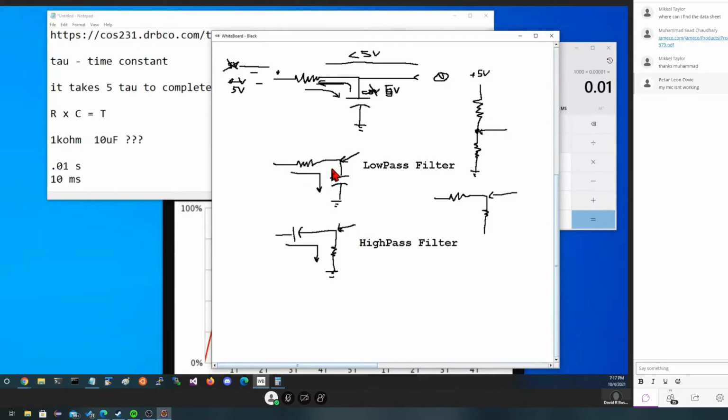Meaning that from here to here, even if you're passing very slow moving signals, like DC, where it doesn't change at all, we will see the result of that right here. It'll basically be the same as though that signal coming in is filling this up like a bucket. And when it's finally full, basically anything passes through. The only thing that could cause that to change would be if we sped this up, uphill, or we slowed it down, a downhill type of voltage. We could control how much voltage is being maintained inside of this. Now, we might add to this something like a resistor in parallel to it with a high value that would, when no current was going into the bucket, let it escape. But we won't worry about that right now. Just we know that this circuit could be made fancier.